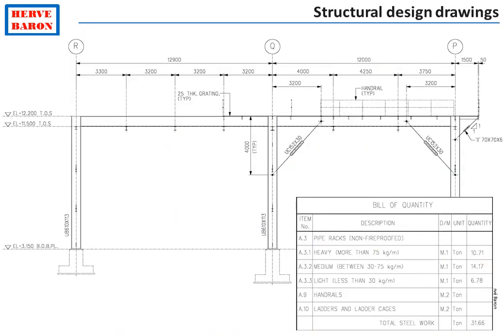These are called design drawings as they do not show all details. In particular, they do not show the details of the connections between steel members, the number of bolts in particular. This will be left to the steel structure manufacturer, which will perform these calculations and issue all the detailed drawings, including piece marks, that will be used at site for erection.